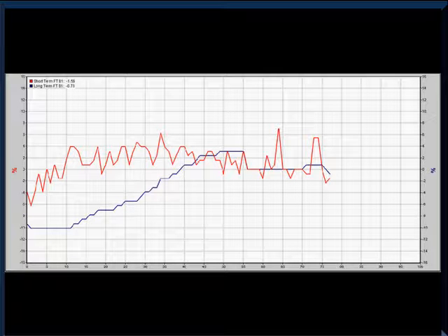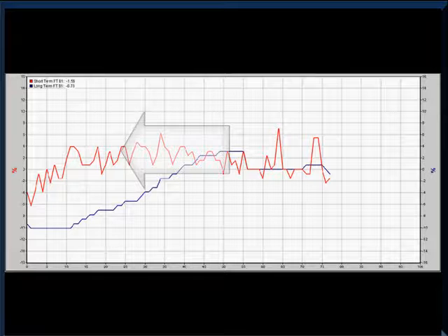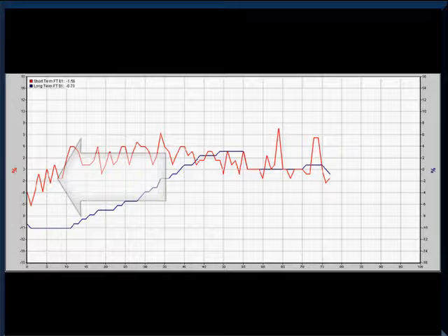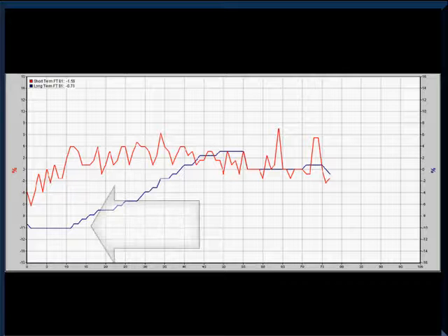Then it started going up. But notice once short term starts leveling out, when long term starts coming up, it's bringing it back into range. So here's what we said. The red one responded to changes in the oxygen sensor. That's short term. The blue, long term, did not react until the short term had been wrong for a period of time, and then it made corrections to bring them both back to 0% ideally.